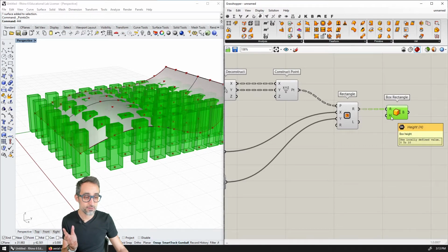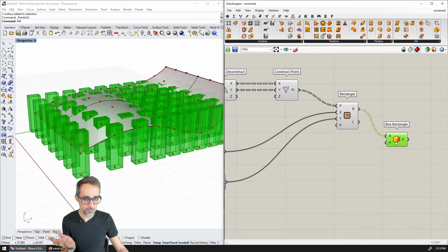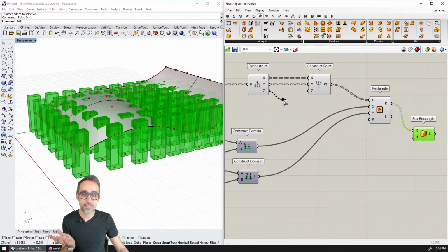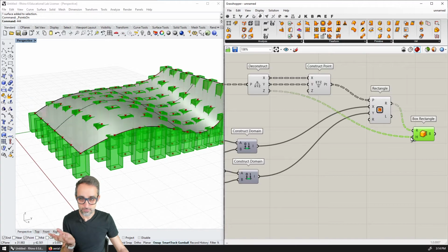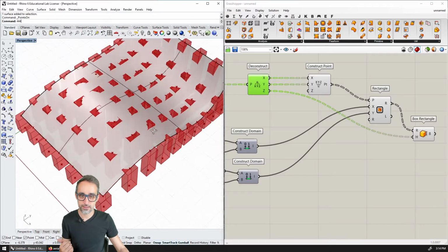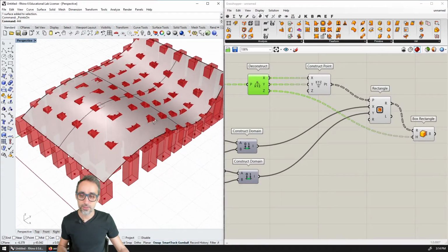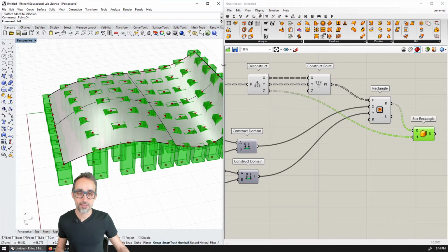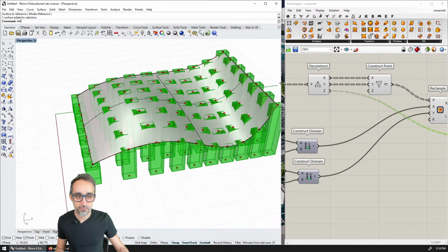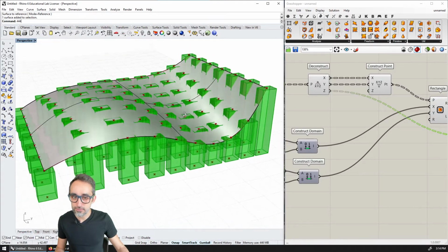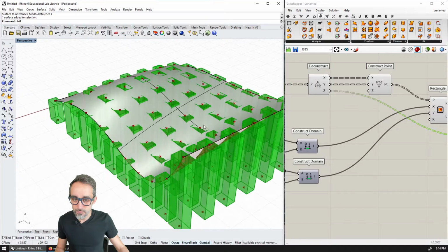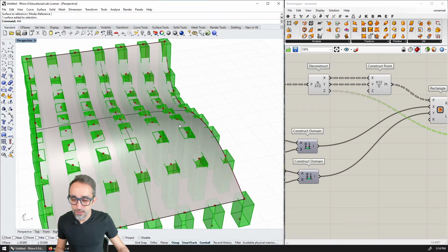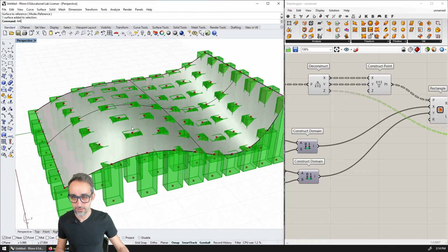And then the height, instead of being 0 to 10, is going to be 0 to the C height that I have for each one of the points. Remember that each one of the points had a C height, and then therefore now you can see that all these boxes are closed, and that each one of the boxes at the center is actually showing here, and it's tangent. It's not tangent exactly, but it's coincident with that point on the surface.